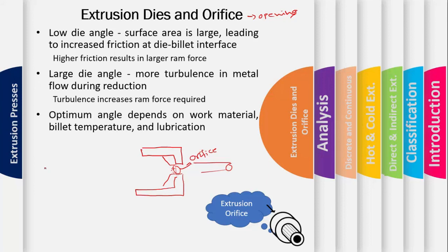That shape factor kx, as we have discussed in the case of forging and others as well, is equal to 0.98 plus 0.02 times (Cx divided by Cc) whole exponent 2.25. That is called a shape factor.